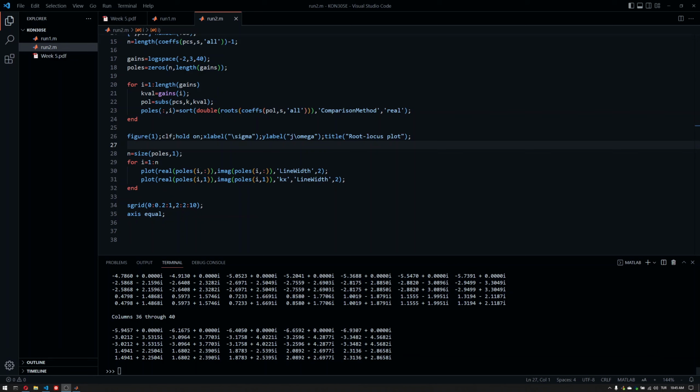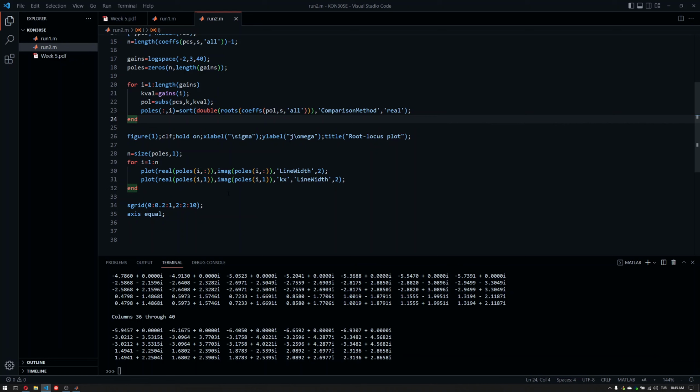Of course, for the root locus plot, we can just get away with this sorting, but if it had been a different case where we have to associate the poles, this might not work, because we know that each pole or root on the root locus has a continuous path, and I can therefore use this ordering, but it is not applicable to all pole association problems that you might encounter.